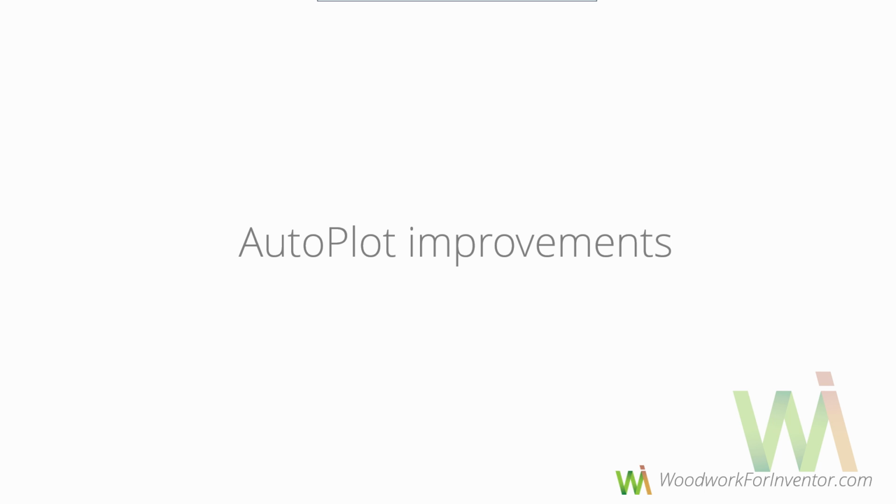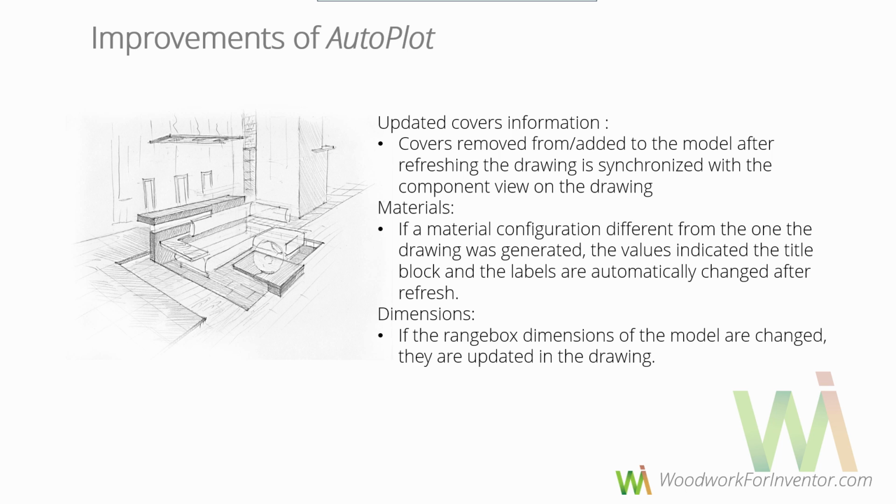And now let's move to the next question about an Autoplot. So the Autoplot is the tool which allows you to generate a set of drawings in one click of the mouse. So what we have here. First of all, we have updated information about the cover, which means that if you remove or add some cover on the model, after refreshing the drawing, it is synchronized and shows the component in the exact condition. So if you remove the cover, it disappears from the drawing, and vice versa.